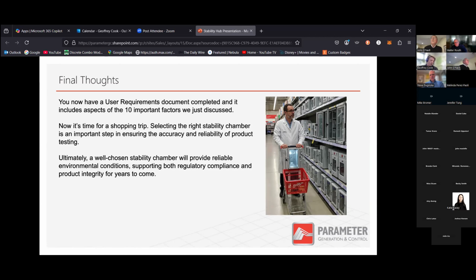Yes. So the inside of the chamber versus the inside of the air handler can be a little bit different. The use of bleach is something that we sometimes recommend, but is sometimes not allowed depending on what you are storing in your stability chamber and the impact that might have on the mold growth is definitely something that we have dealt with. If it is an accelerated study, if your stability chamber's air handler has the capability to run a range, if your accelerated study lasts 6 months, at the end of the study, you can actually tune your machine to dry the entire room out and kill all of that mold.